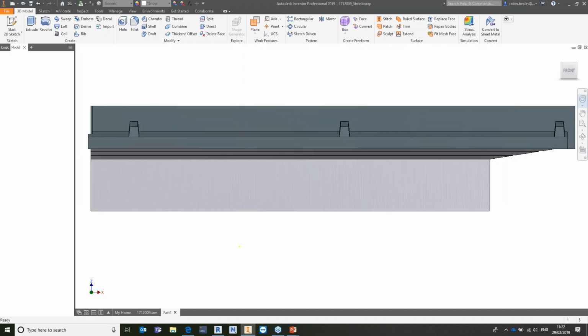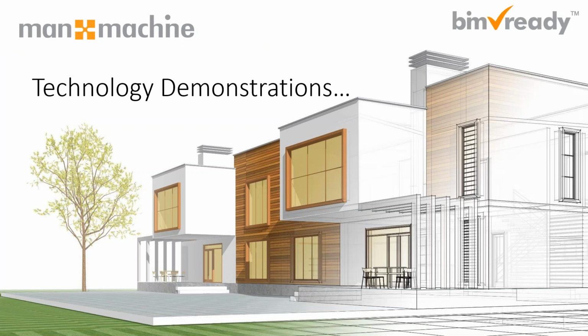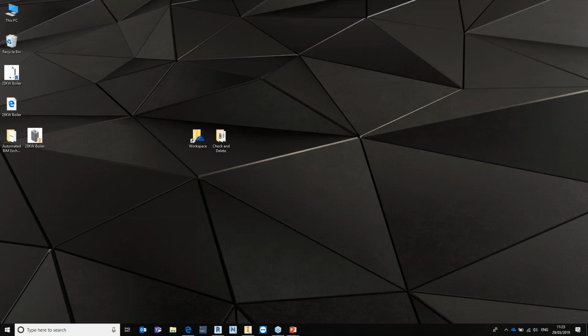It's stripped out the wall. It's gone into BIM Exchange. It's shrunk the component. It's changed the front of the view cube to match the front of the model. It's adding all of the properties in the background. It's adding all of the level of information. It's making sure the level of detail is matched. And this is now going to create an RFA file, an IFC file, and an ADSK file from Inventor.